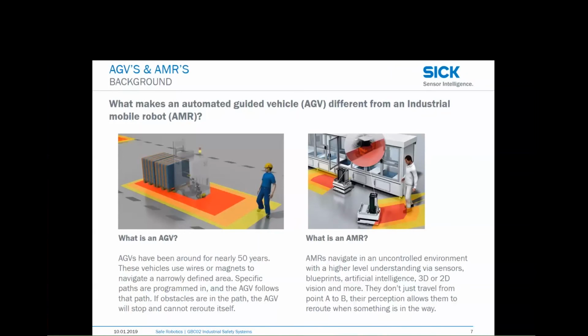They can use AI, they can use path planning, they can use other implementations of technology to help them navigate through a facility, and therefore can find the most efficient route, considering other influences to the space like people or blocked hallways or even other AMRs operating in the area. So they'll follow suggested paths if they exist, but they do have the freedom to find their own way through the facility to get from A to B.